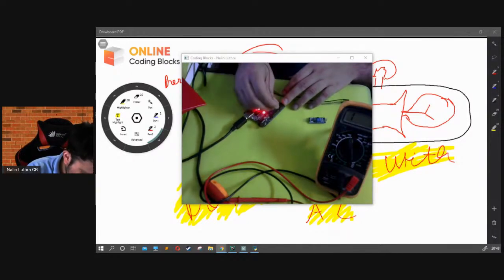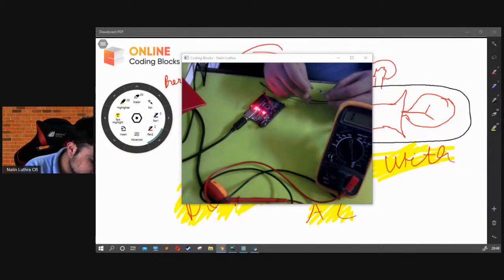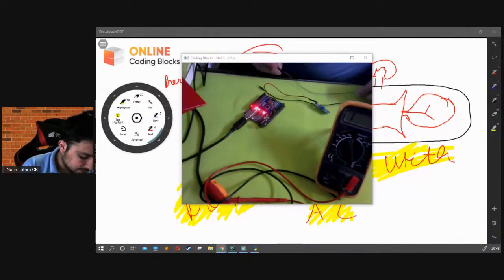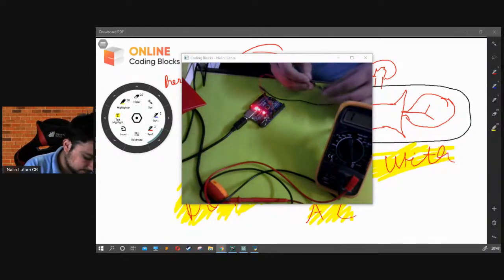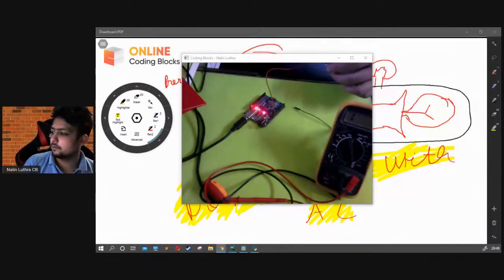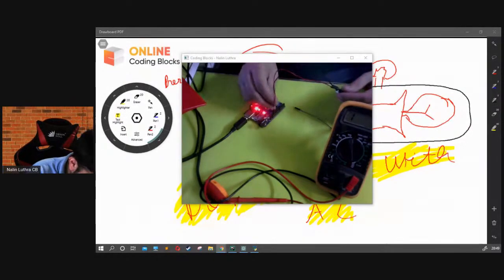Let's connect the 5 volts first here. So we have VCC over here. Let's connect the 5 volts with it. That's good, 5 volts is good. Now I'm connecting my digital pin with it. So let's go with digital. First let's connect the ground one. Okay, digital can be connected later maybe. So let's get it done. This ground connection first of all, and it should be up.